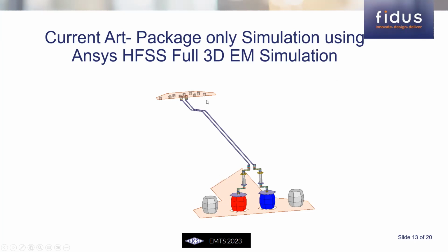If you look at this package closely, for most applications, we generate the S parameters of this package by simulating the circuit that I've shown here. Ports are placed on a reference plane, usually defined on the die side, and another reference plane on the package side. Ground balls provide the return path continuity on both sides. And this is generally simulated. And this works very well even up to 25 gigahertz. But as the frequency starts increasing, this approach gives you the S parameters all the way up to the BGA balls.